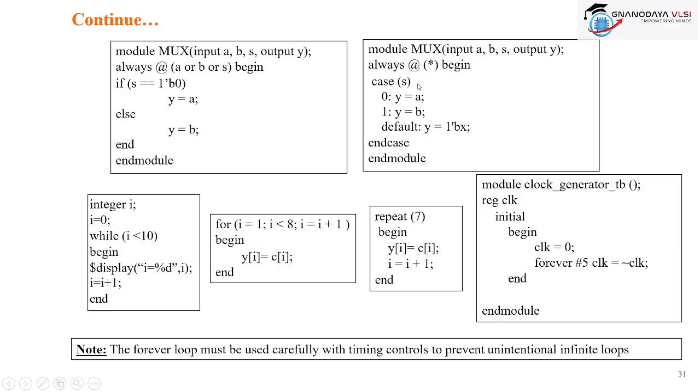Here I can use a case statement also. So I can use the operator star, it will be applicable for all the inputs. Case s: 0, y = a; 1, y = b; default is 1'bx. This I will explain, why it is written, because of the latch.